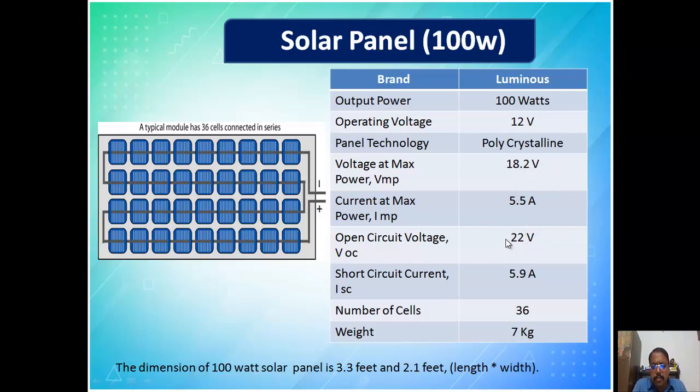I have already told you, open circuit voltage is nothing but connecting without any load, just keeping your multimeter between the positive and negative. That is open circuit voltage. But if you give any load, automatically your potential will fall. Similarly, short circuit current means the load doesn't have any resistance, 0, and again that condition is also not possible.